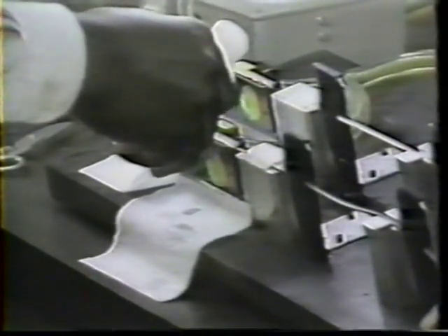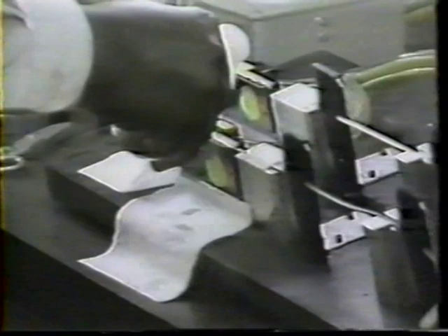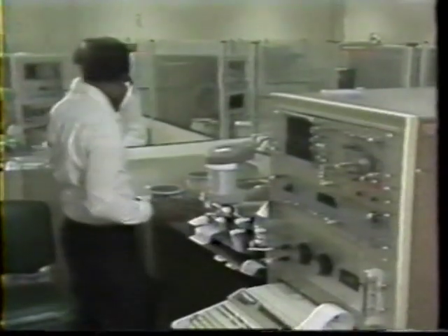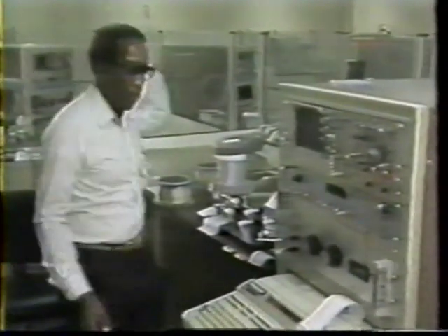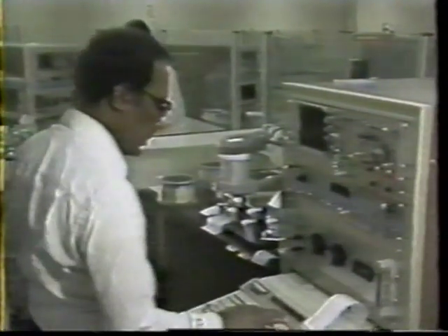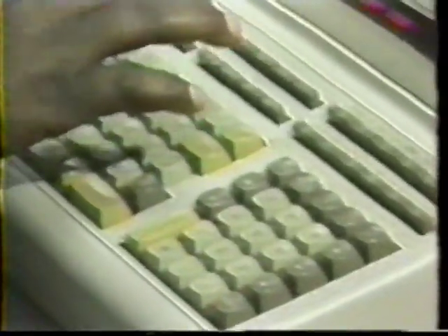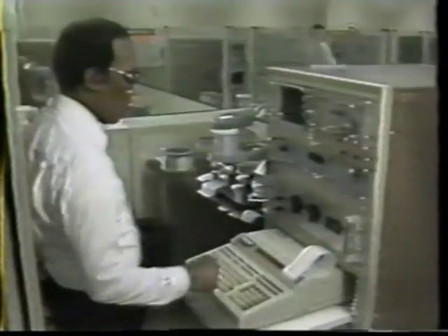Test number 3 measures the light guide's bandwidth, which may be defined as the bit rate or information carrying capacity of a light guide fiber. The more information carried per fiber, the more economical the light wave system. This test is conducted using 2 different light wavelengths.